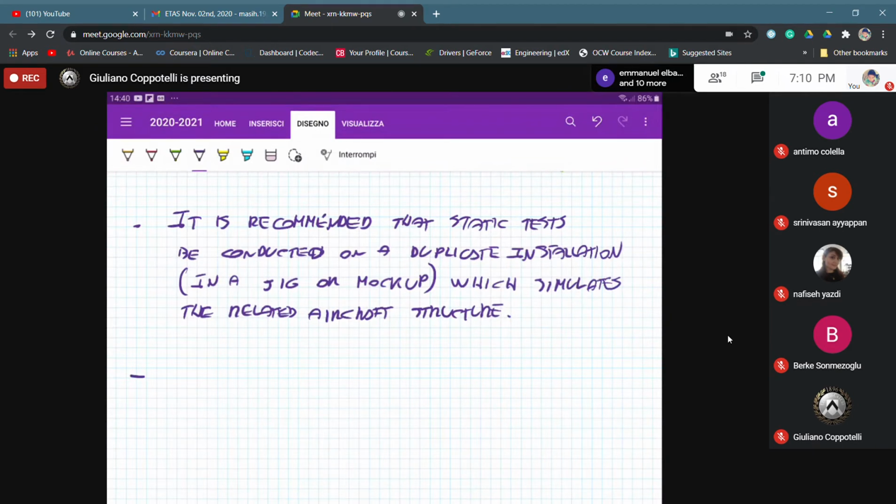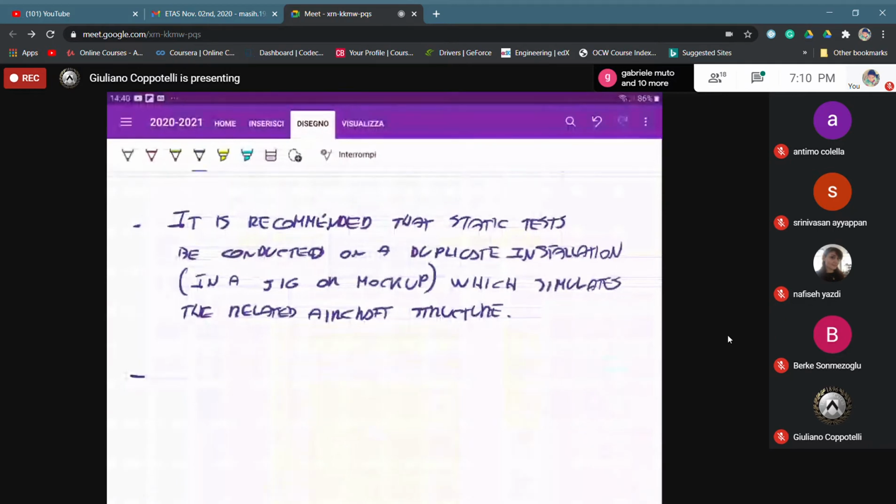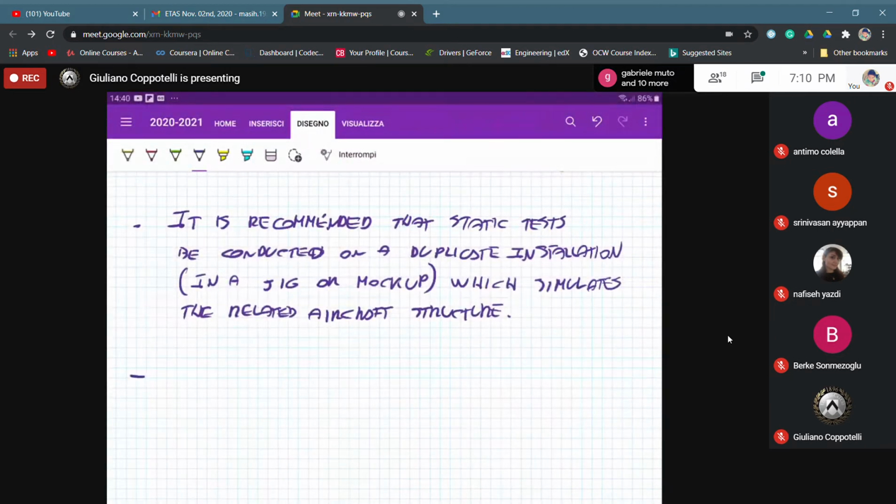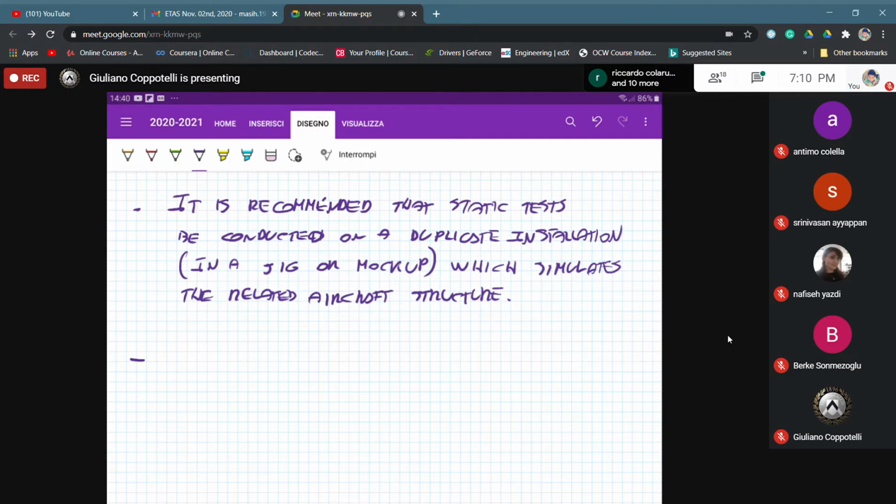However, talking about the external loads, these must be discretized into some lump loads, and this law should be actually the replication of what is happening in real life, that is, all the continuous load from the inertia, from the elastic reactions and whatever, should be moved from continuous to lump.